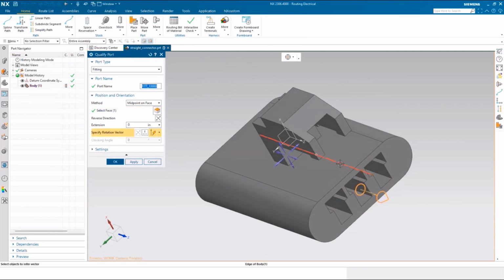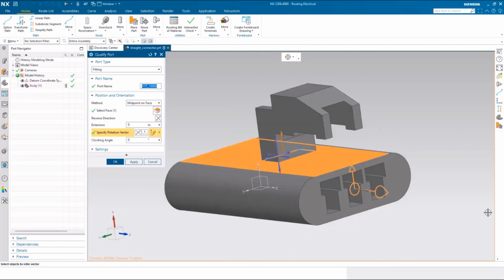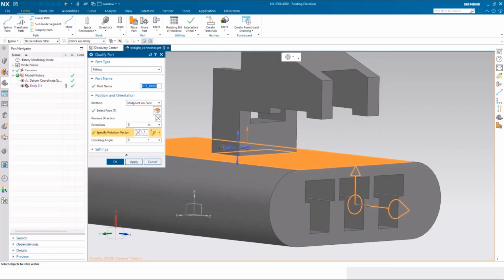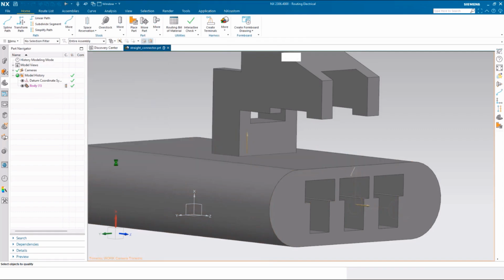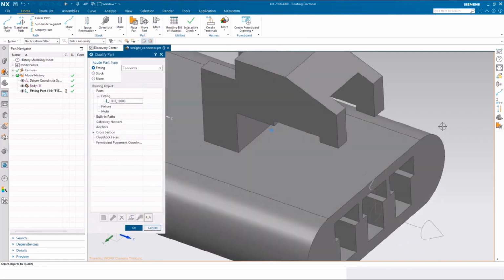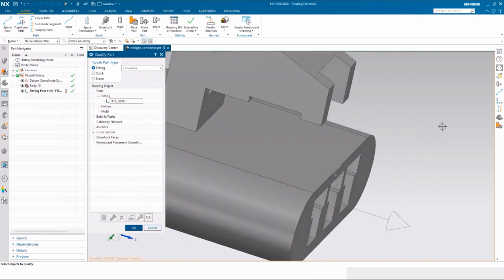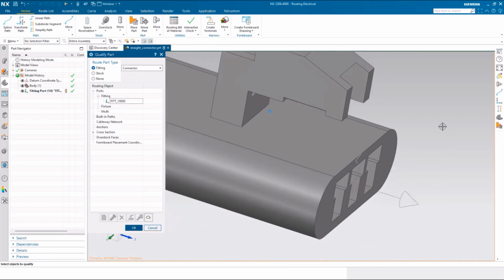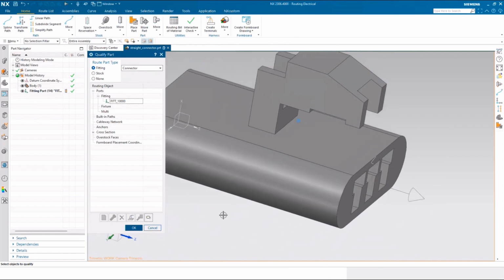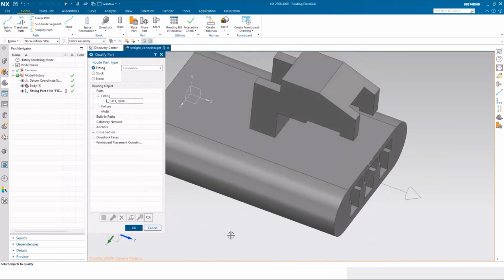And let's specify a face here, and I get this little upward vector that you see there. Based on that vector, I might want to allow for different 90-degree rotations of the part to get it into the right position when I add it to my assembly. So let me go ahead and add that. Okay, so that's the first port. You see it there. That's where those arrows come from if you see any kind of qualified parts in an assembly. So that's just a simple port.